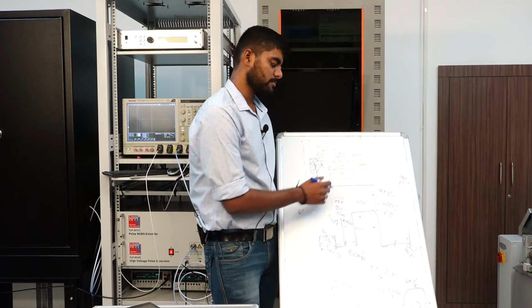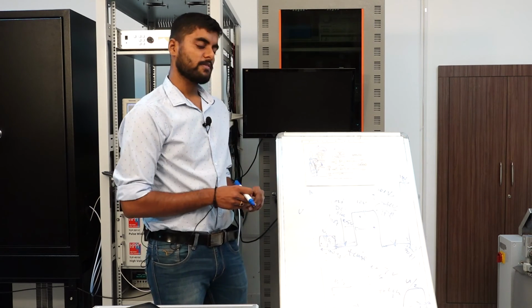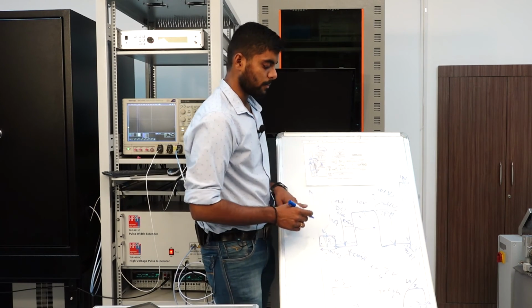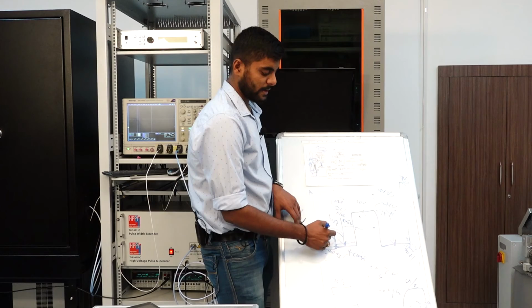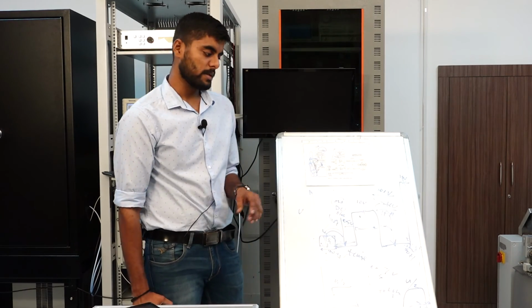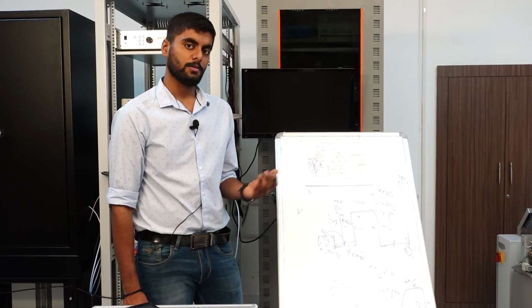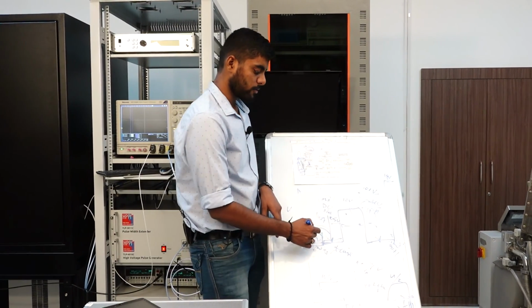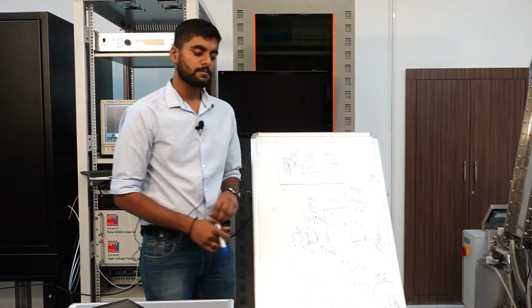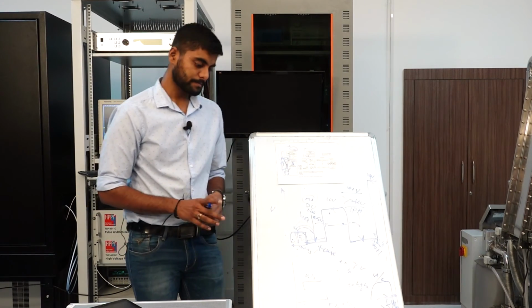So that's why this leakage test is important, and that shows you the importance of the switch as well, because the switch is the component that is going to alternate between these two measurements every time. It's also going to measure the signal as a pulse signal. It has a role in measuring the pulse output from the DUT through to the oscilloscope. So that's why the switch is one of the major components in the TLP setup.